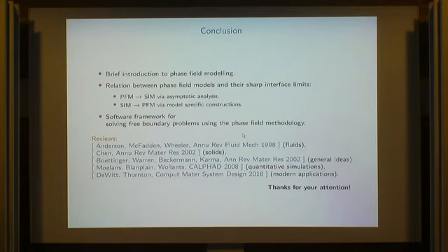Moving meshes in a bulk mesh. Either you can use these fitted approaches like Vanessa had it, where the surface mesh is the boundary mesh of the bulk mesh. But this has to be set up. Or there are the other unfitted approaches where you just have a standard bulk mesh and then the moving surface mesh that is moving through it.